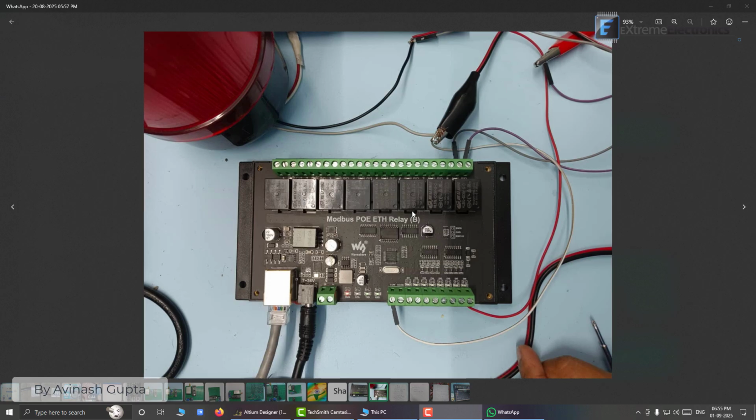And we will have a driver for the relays, because a microcontroller or shift register pin cannot directly drive those relays. So we will be using a driver chip like ULN2003 or ULN2008, which has 7 or 8 drivers, okay. And over here we will have screw terminals, and these will be connected to each of the terminal pins of the relay.